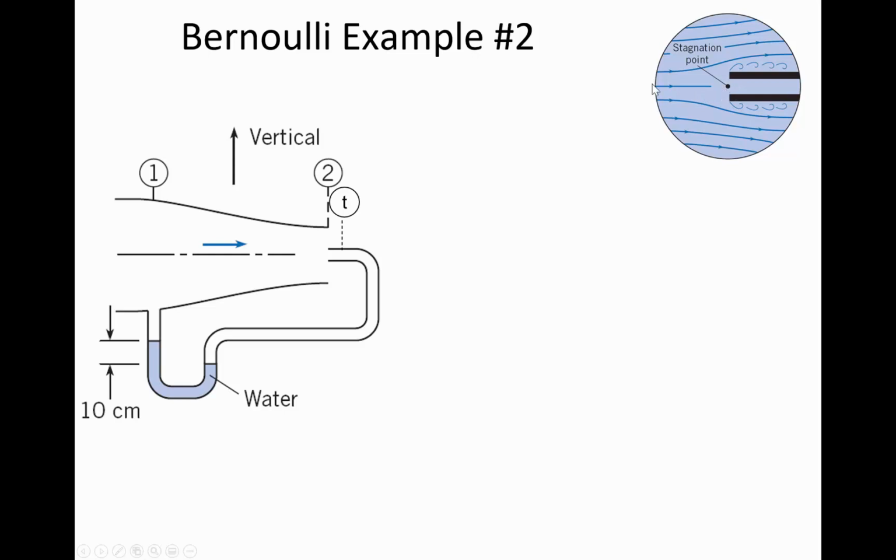It had velocity upstream. Downstream there's zero velocity, and so there's a localized increase in pressure. And that's what's causing this deflection: the localized increase in pressure at the stagnation point forced the water down on the right. And so that deflection arises because of the transfer of energy from the velocity head to an increase in pressure here at the throat of the nozzle.